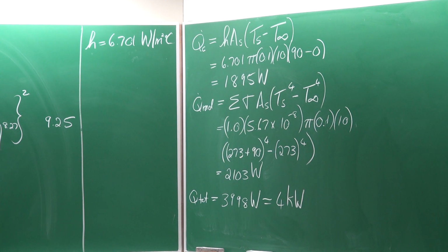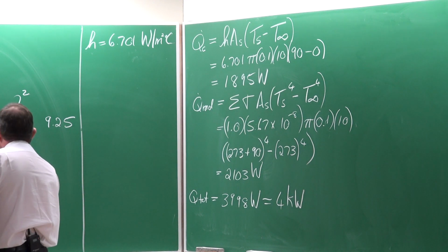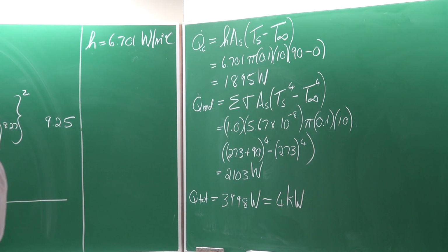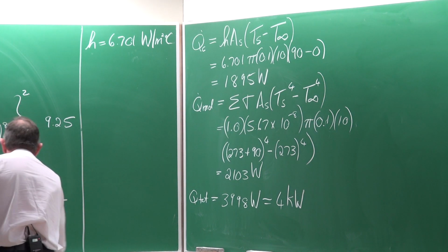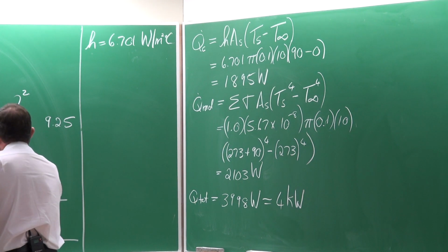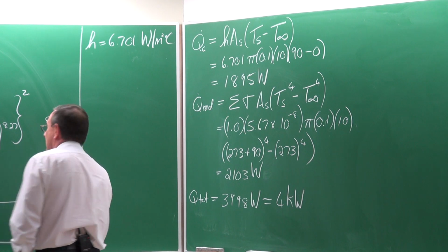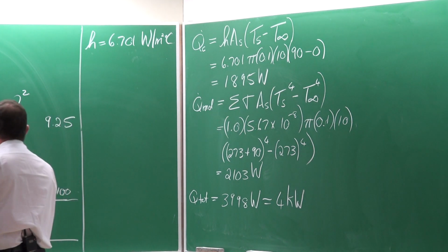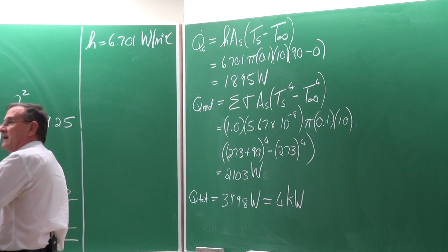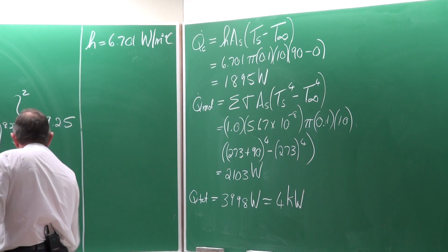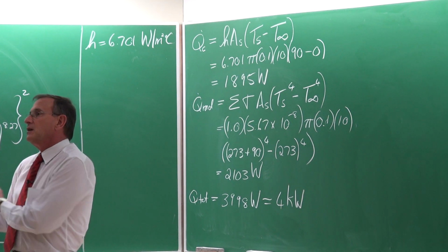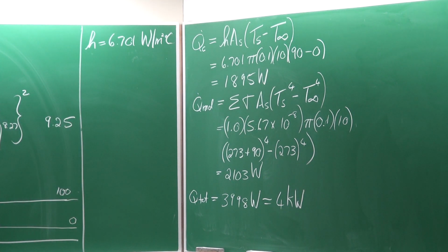Well, in this case, if you can just imagine the outside surface, the surface temperature it has been given is 100 degrees Celsius, and is constant. So if you go and plot it, that would be 100 at the beginning of the pipe, and at the end of the pipe it will still be 100. The other source of temperature is that of the air, and that is in a room. So there it will also be 0, and there it will also be 0. So do not confuse natural convection with using the LMTD from the convection cases.